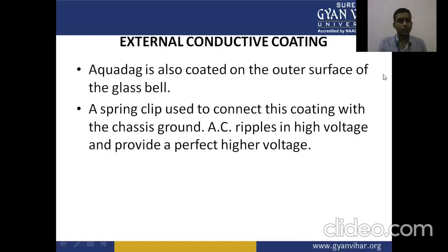External conducting coating. Aquadag is also coated on the outer surface of the glass bell. A spring clip is used to connect this coating with the chassis ground, which removes AC ripples in the high voltage and provides a perfect high voltage.